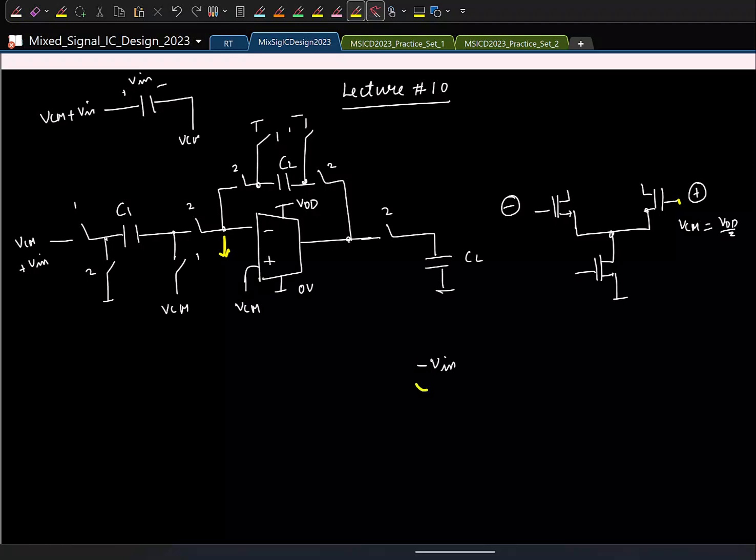So it is good that it is responding to only the signal, but we have to add the DC bias or the common mode on top of this also. So this is what we want the voltage to jump to. So what will be the change you make? So again, if you think about it, since we are connecting it to ground, this jumps to minus V in. If I raise this to VCM, this will also rise by that voltage. So we'll do this. By the same token, usually all the things that are connected to ground are usually the common mode. When we are drawing it as ground, it just meant that in small signal it was ground.